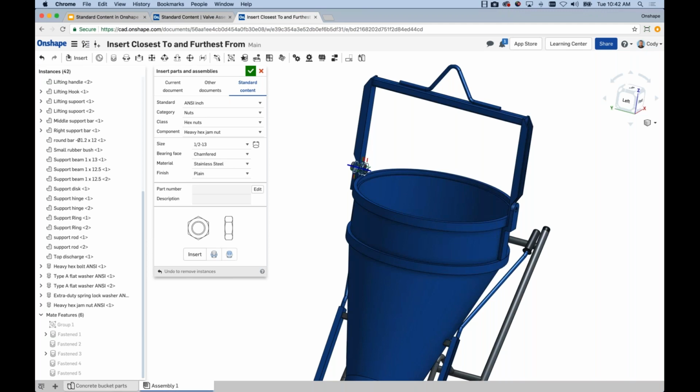If you're taking the information that you insert here and you're trying to use that to generate a true parts list that can be used to make orders and things like that, then getting the number of nuts and bolts and washers into the BOM is an important detail. And so the big thing I would stress about this is, getting all of that metadata in is very easy. As of today, you can edit the part number and description of any piece of standard content that you insert, and it will propagate automatically throughout your company.